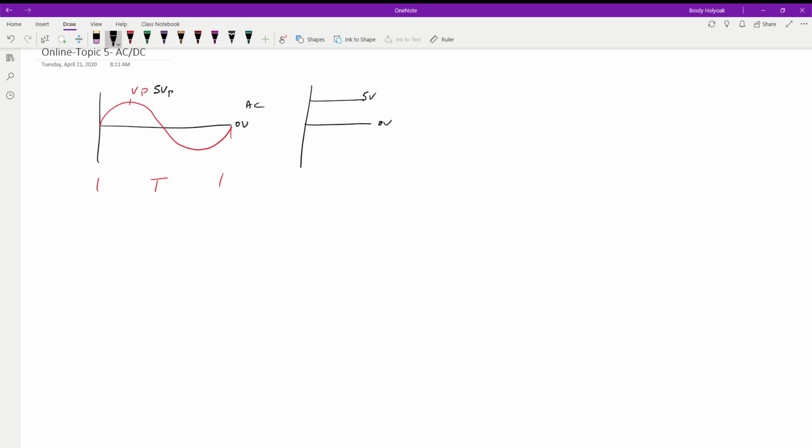Now, one of the things we need to do when we're working with these two values and combining them together is make sure that we list the DC portion specifically so we can find it, and vice versa with the AC. With the AC signal, it's pretty easy because we have our 5-volt peak, 5-volt peak to peak, and RMS. We've got the different designators that we use already. And just so we don't accidentally mix things up, when we're talking about the DC portions, we can label them as VDC, a quick visual reminder that we're talking about the DC voltage versus the AC voltage for any of the situations that arise.